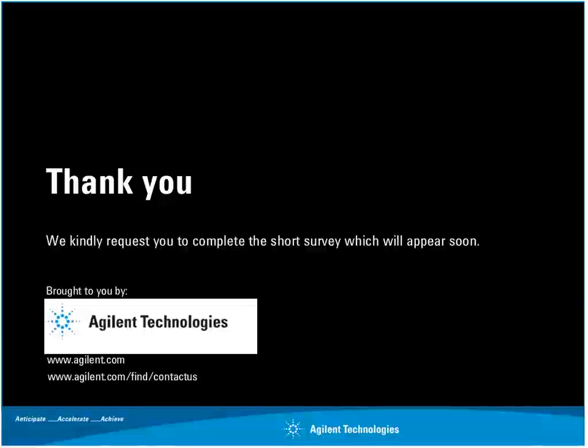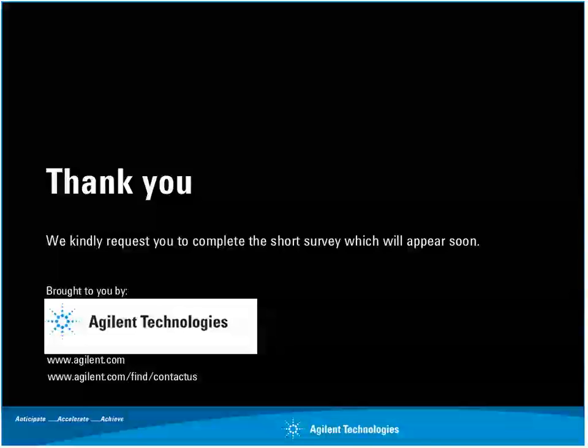For instance, if your signal rise time is, let's say, around 30 nanoseconds, then you can expect the error to be less than 10% or even less. And the error becomes insignificant when your signal rise time is more than 90 nanoseconds. Okay, I hope that answers your question.